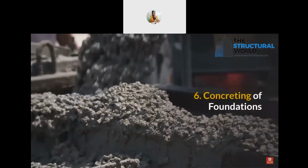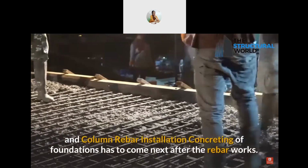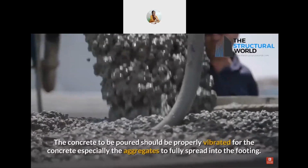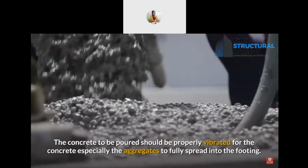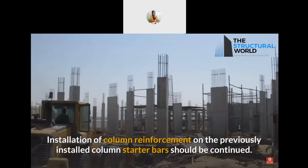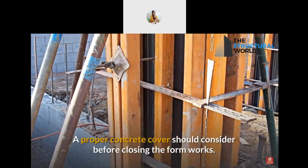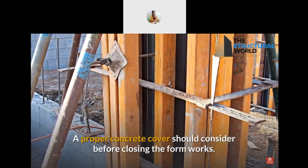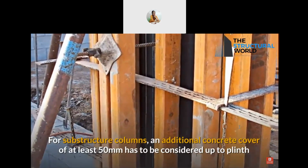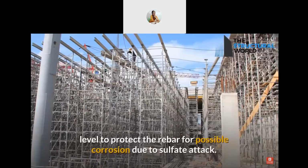6. Concreting of foundations and column rebar installation. Concreting of foundations has to come next after the rebar works. The concrete to be poured should be properly vibrated for the concrete, especially the aggregates, to fully spread into the footing. Installation of column reinforcement on the previously installed column starter bars should be continued. A proper concrete cover should be considered before closing the formworks. For substructure columns, an additional concrete cover of at least 50 mm has to be considered up to plinth level to protect the rebar from possible corrosion due to sulfate attack.